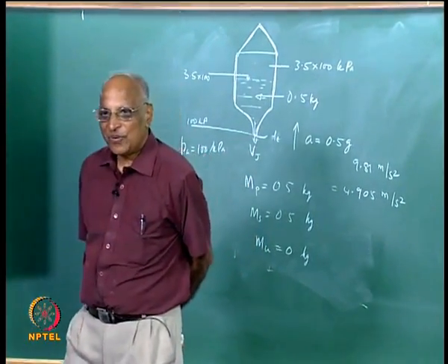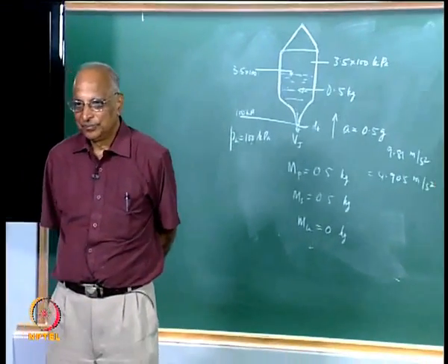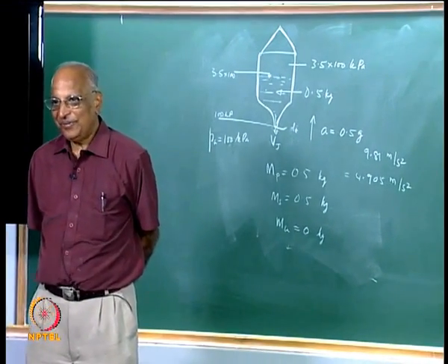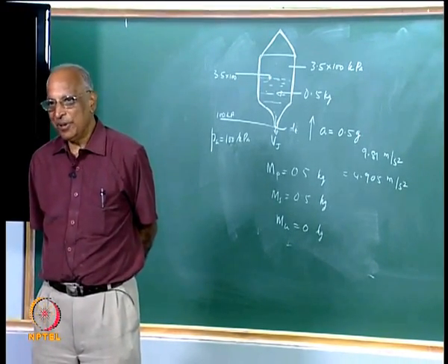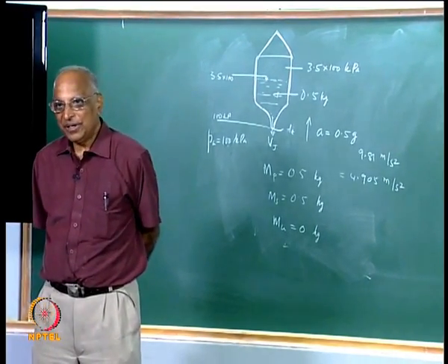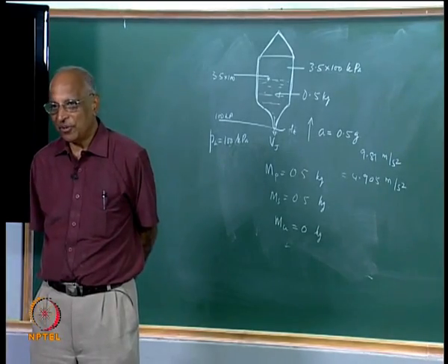Therefore, F is equal to m dot kg per second into what? How do you calculate the force? We have done it. Change of momentum, m Vj is momentum, force is equal to d by dt of m Vj, which is equal to m dot Vj.